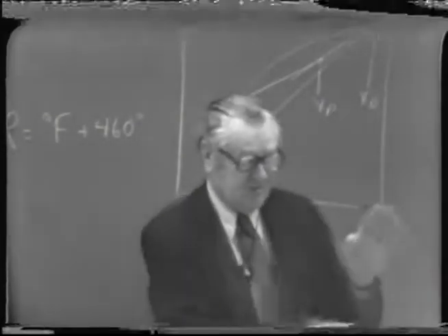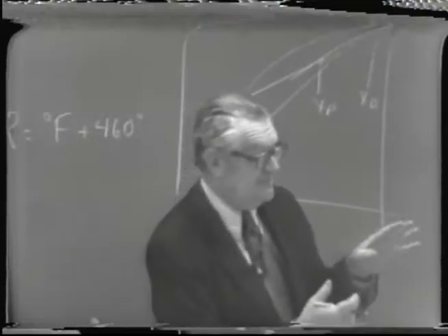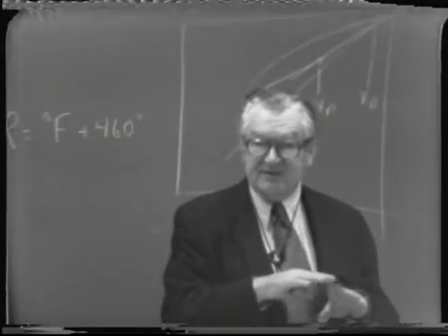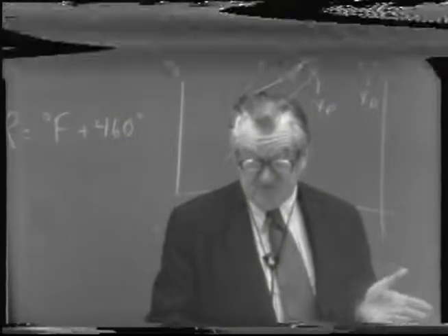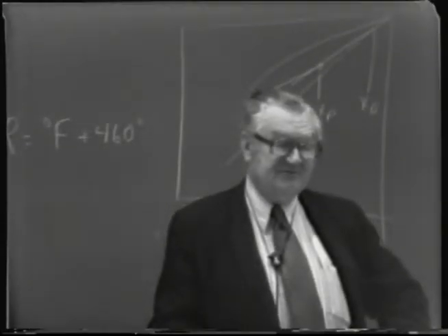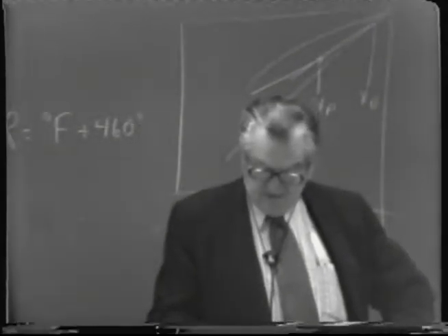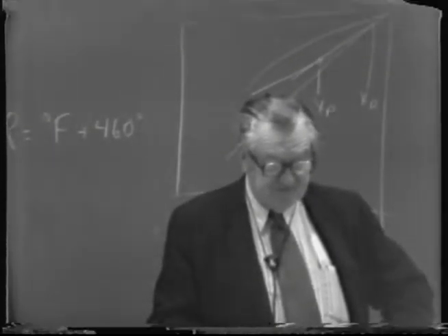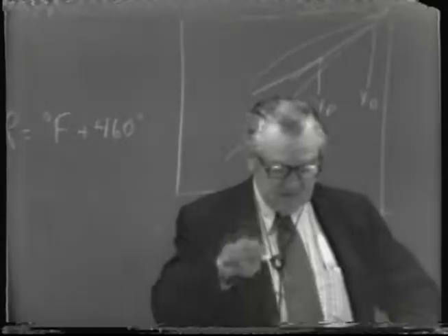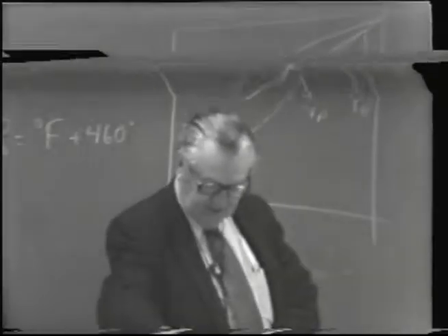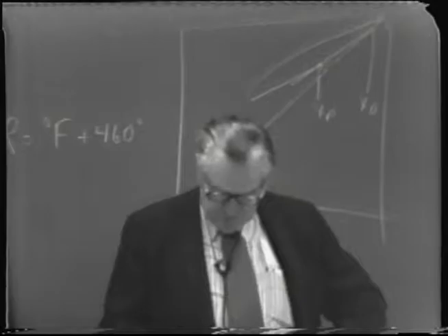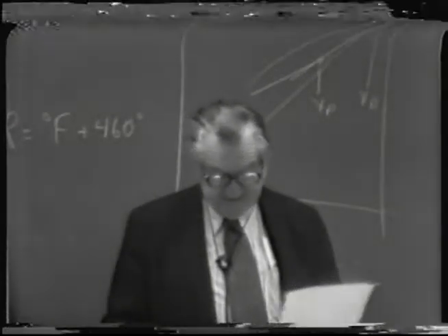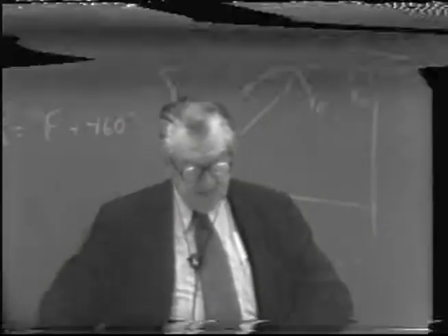Actually, the temperature varies somewhat through the column, but I took the temperature which would exist at the highest temperature, which would be down near the feed tray, down near the bottom. And if you look up in a table, you'll find that would be about 190 degrees Fahrenheit. The boiling point of about 7% alcohol, I imagine, that was at the feed rate, the concentration down near the bottom. Anyway, the result comes out to be 122 cubic feet per second, the overall volume rate of the vapor. The top of page 4.